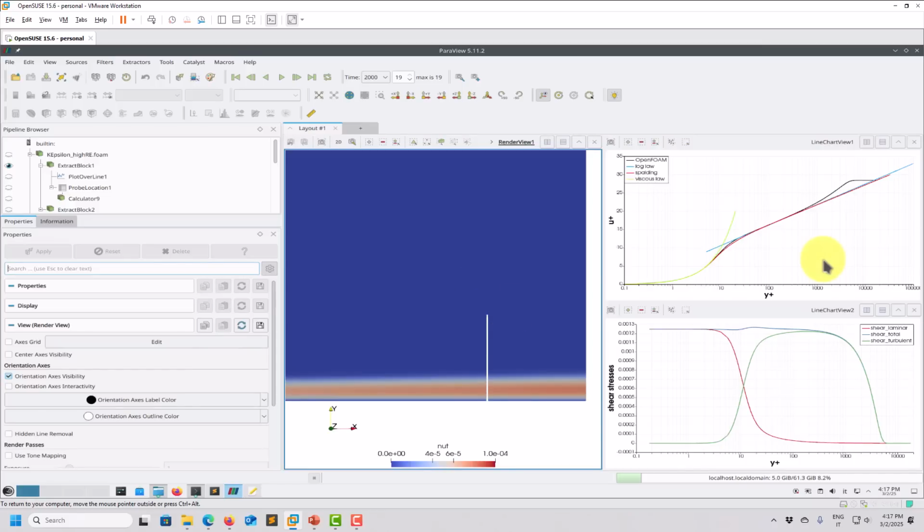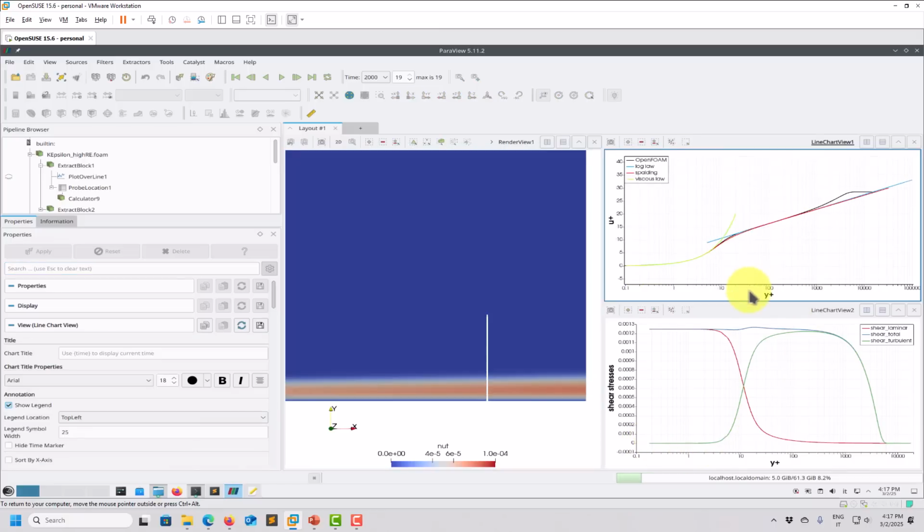And there you go. So now it's wall resolving. Your budget of shear stresses, everything makes sense, nothing is strange. Look here, we can zoom in and we have the function. The black one is our solution, then doing the blending, buffer layer, and then resolving the viscous layer. There you have it. Okay, so probably also check the wall shear stress. I don't recall if I updated, but at this point it should be straightforward to do that.